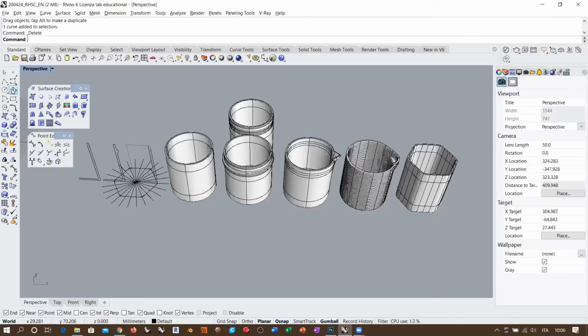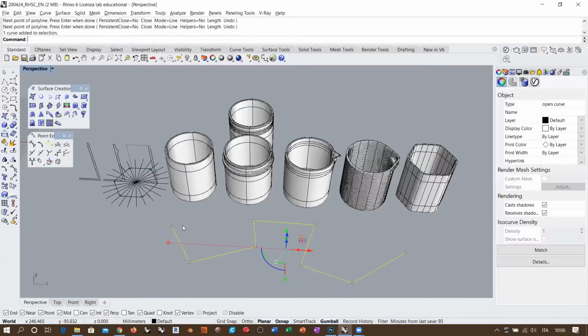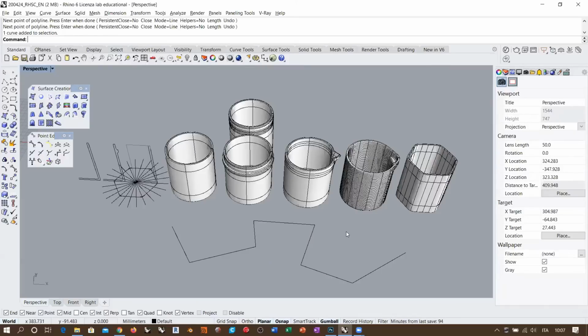In general, if you think about it, the polyline is another particular case in this sense, in which you have a degree 1 curve, and a set of knots which in this case are coincident with the control points. Why? Because we saw that in a degree 3 curve, the uniform knot vector contains only a sequence of values that never repeat along the vector, with the exception of the first knot and the last knot, which have full multiplicity.